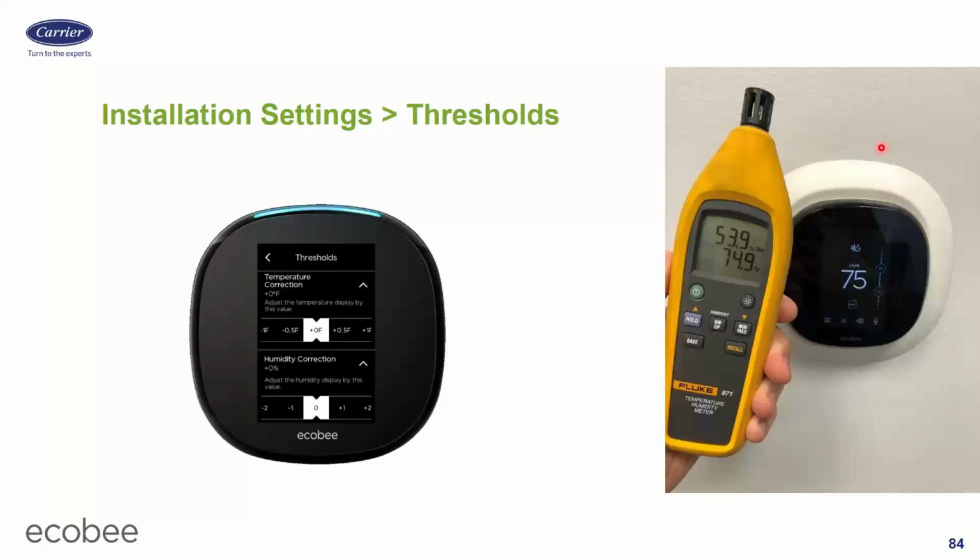Assuming you've got rid of that issue and that's not the problem, and you don't have a diffuser blowing right on the thermostat or anything weird like that, and you just want to tweak the stat to match something else, that's where you'd come into this temperature correction, and you could add or subtract however many degrees in half-degree increments. So if the customer thinks it feels like 77 in there and your thermostat says 75, I'll come into here and I'll put +2. The 75 on my stat will now start displaying 77. It'll control to 77. The customer will be happy.